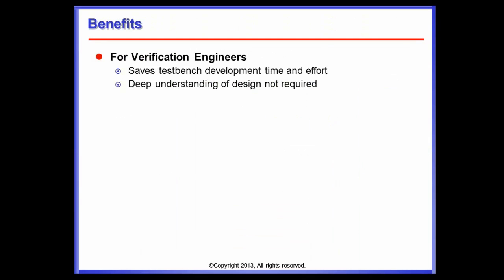The benefit is that you can experiment with this and tackle your design, because in that case 15 passes. But if you then make a slight change in clock frequencies or reset alignment, you might immediately have a failing case. And if you detect that in the back end, or in netlist verification, that's a long way back to change the counters and test whether it works or not.